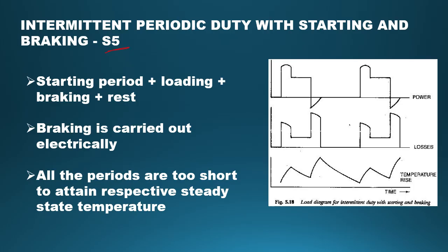The next one is the S5 duty cycle, that is intermittent periodic duty with starting and braking. This is basically the same as the previous duty cycle, but here the braking is carried out electrically, as in the case of VFD motors that use electrical braking.